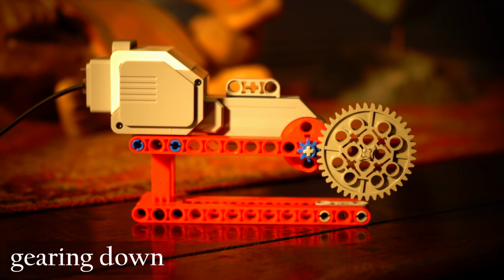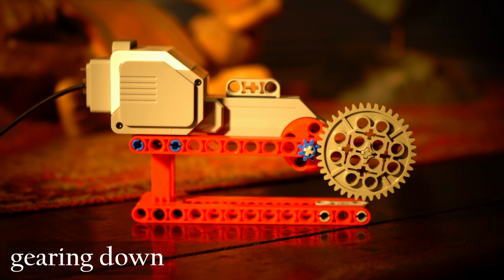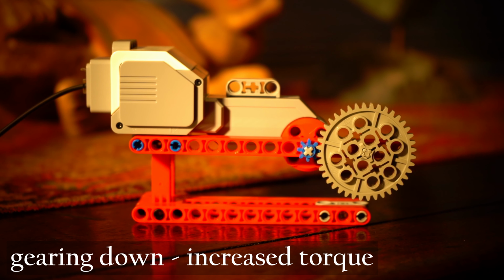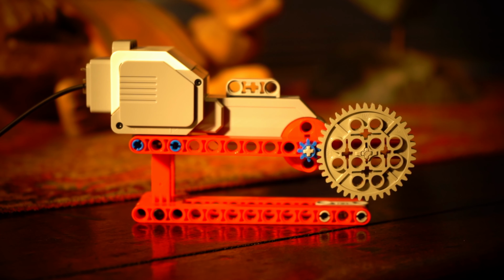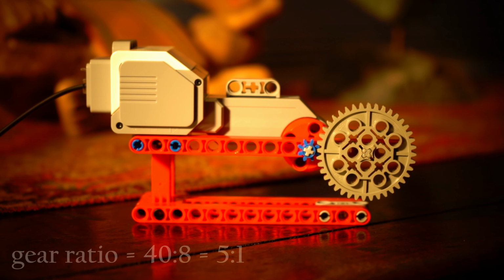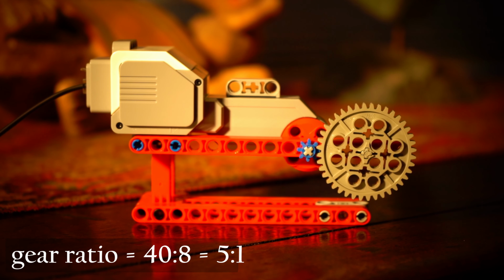Gearing down occurs when a smaller gear drives a larger gear, in which case the gear ratio will be greater than 1. Gearing down reduces speed while increasing torque through mechanical advantage. In this simple gear train, the two gears have been reversed, and the 8-tooth driver gear now powers the 40-tooth driven gear. This produces a gear ratio of 5:1 and a mechanical advantage of 5.